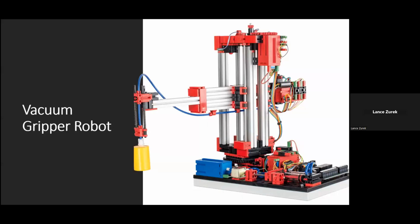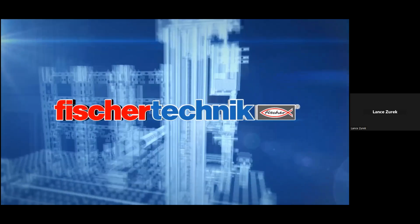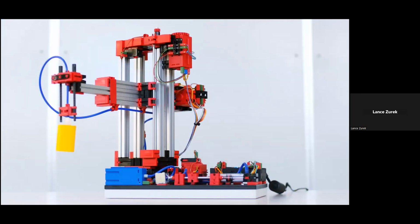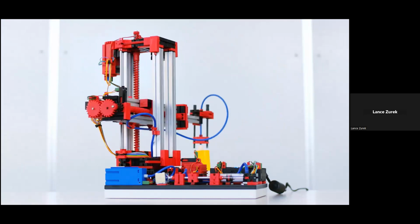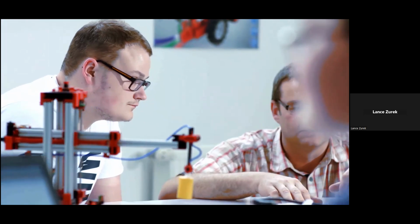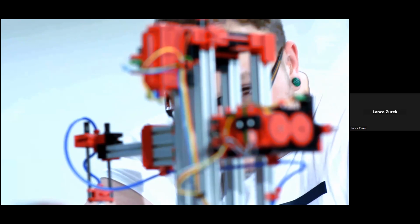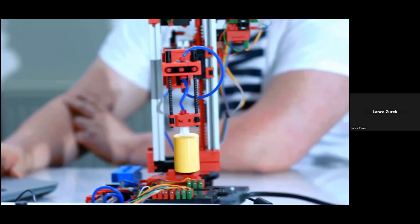First model we're going to look at is the vacuum gripper robot. We're going to have a video going here, and as you're going to see in the video, the vacuum gripper is a 3-axis robotic model with a vacuum gripping device. The model is designed to precisely pick up and position work pieces in 3-dimensional space. The model consists of 3 encoder motors, 3 push-button limit switches, a vacuum suction device, a compressor, which is the blue brick component. When you see the arms spin around, you'll see that, and a solenoid valve.